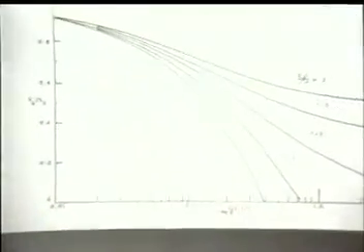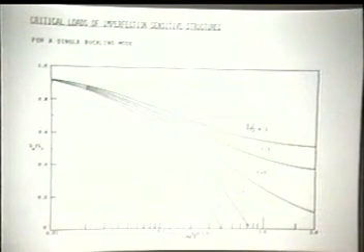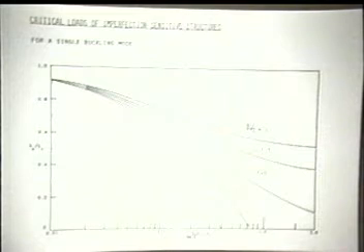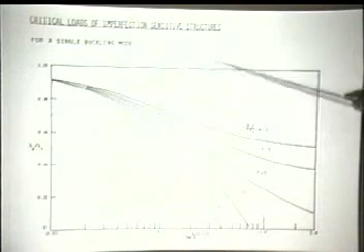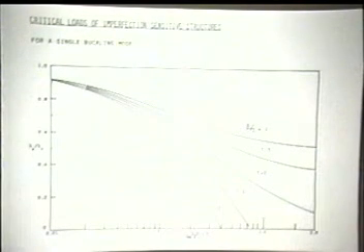And notice what happens if you work with that curve. For very large imperfections, it indicates that the shell will have no load carrying capability whatsoever. Obviously not true. If you are an experimentalist, you know even a very imperfect shell will carry some load. What is wrong? Remember that in the formula we neglected terms of order c bar, so the validity of these curves is only up to a certain value of this parameter.